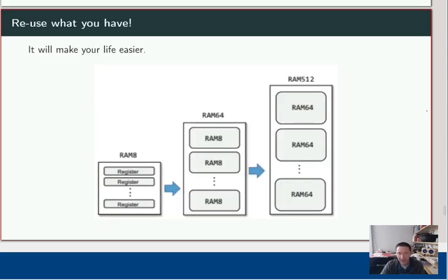Once you have that very basic structure, if you've built up something like a RAM 8 chip, then your life starts to get pretty easy, because kind of what we've done in this class, we had a NAND gate, we built up a few logic gates, then we use that to build more logic gates, then we're using those to build up an ALU, and this, we're going to build up a way to store a register, and then build up a RAM chip, and from there it just starts stacking, stacking, and stacking.